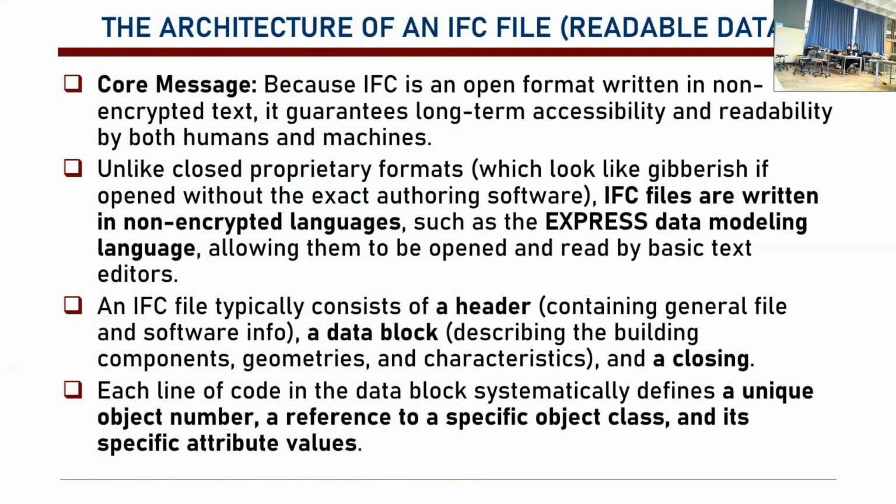So these are all used for creating a common language. It's an open format written in non-encrypted text, so we can read the IFC file in a text editor. You just take an IFC file, put it in a text editor, and you can read it. Open format means it's long-term accessible by both humans and machines. So you can write your own software to read the IFC file.